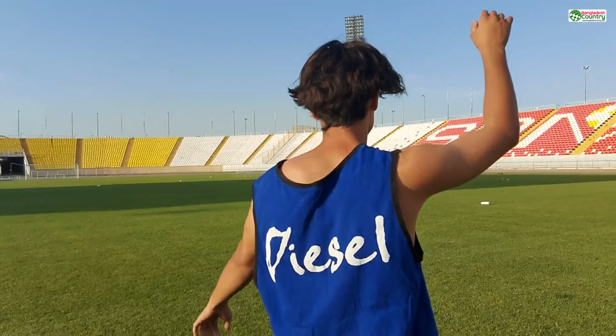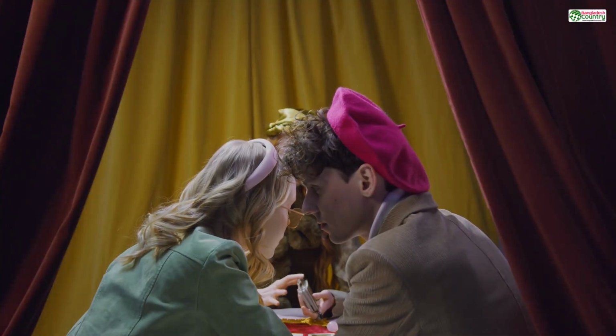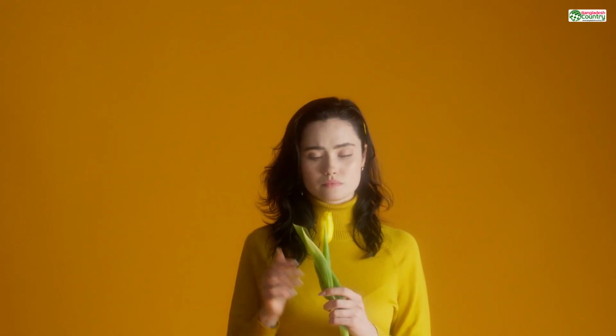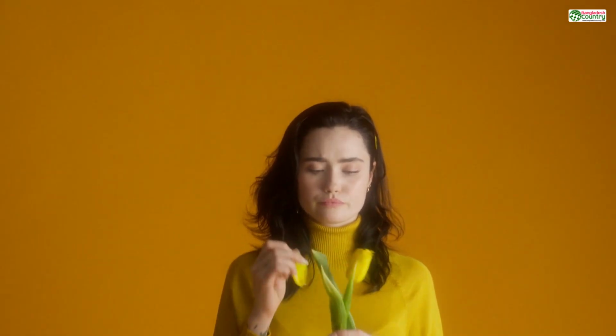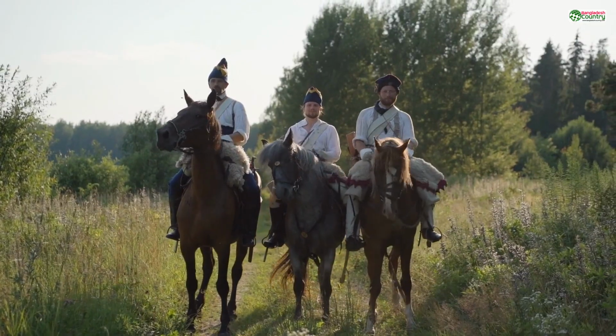That's a flipped normal. When a few triangles on your model are facing the wrong way, you're telling the printer that part of the object is inside out. The printer software sees this, gets hopelessly confused about where the solid part of your model is supposed to be, and generates a flawed print path. So, you've got holes, you've got internal faces, and you've got flipped normals. The three horsemen of the print apocalypse.